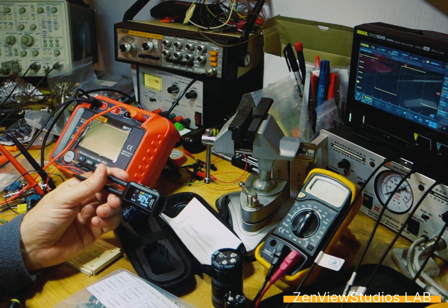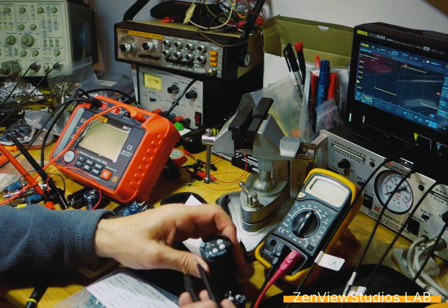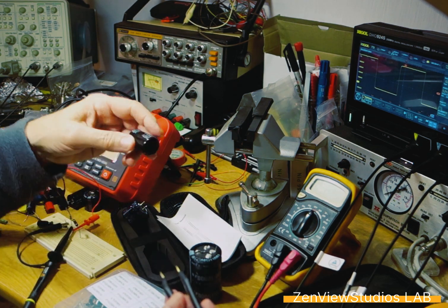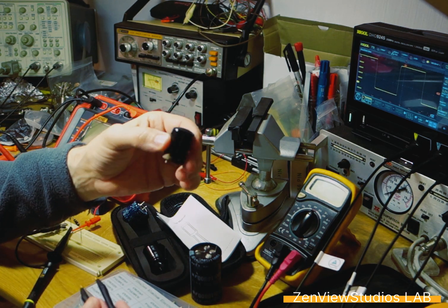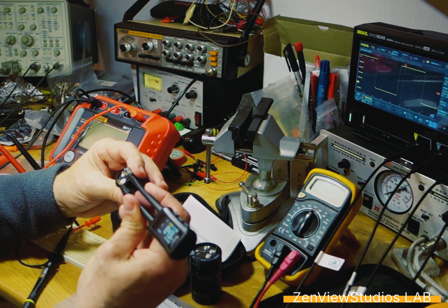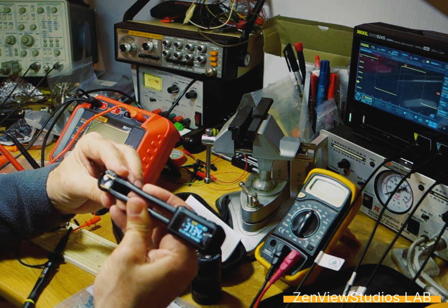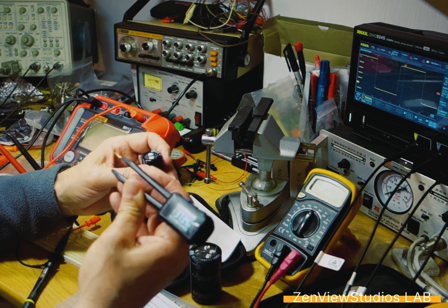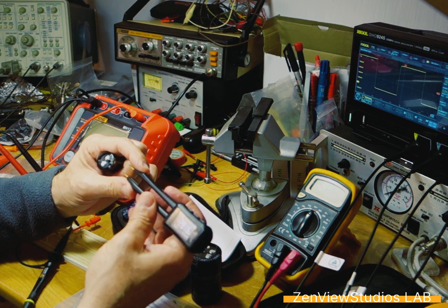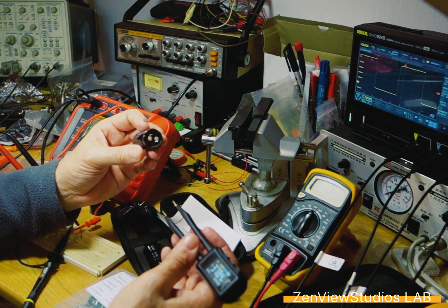It's obviously not the only thing you need to know about a capacitor, because I'll show that in another video. You can measure some caps which might look a little bit wary, and will give proper numbers and ESR which are quite good, but I will demonstrate in another video that this is not enough. So while this is a very nice little gadget to show ESR, it's not the only thing that you ought to know about the capacitor.